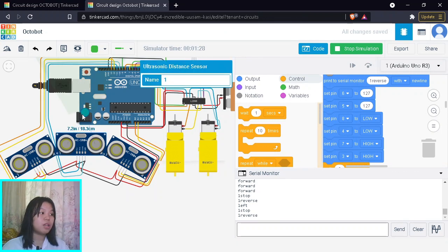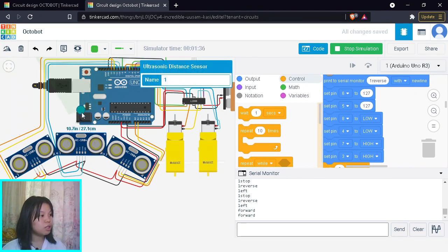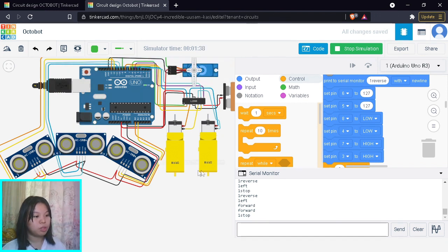Now we look at scenarios 2 and 5, where after checking, both left and right are blocked. So we're going to make our second stop, then second reverse, and then make a U-turn. I'm going to make that scenario: this is less than 20, and this is less than 20. Comes our second scenario, less than 20: first stop at 0 RPM, first reverse at negative RPM at half the speed. Then check left, check right, and then comes my fifth scenario: second stop, second reverse, and then it's going to make a U-turn.